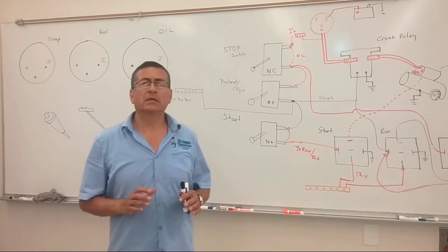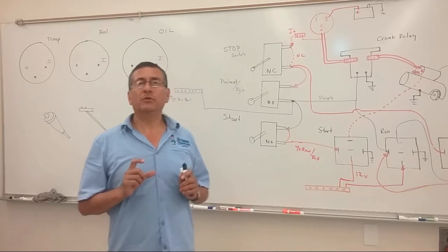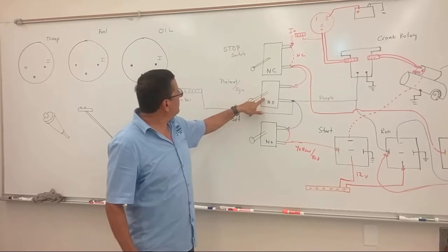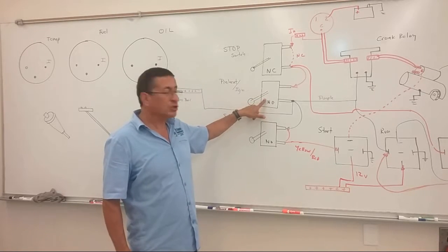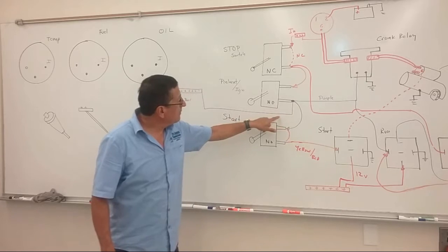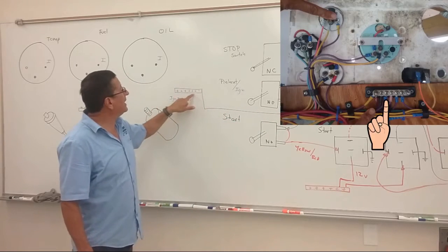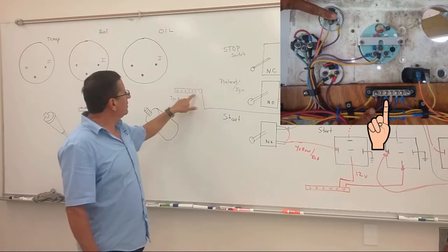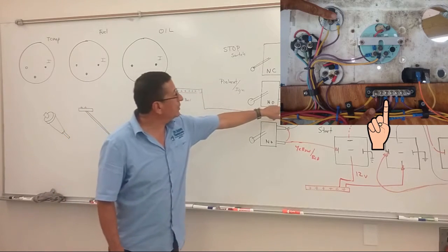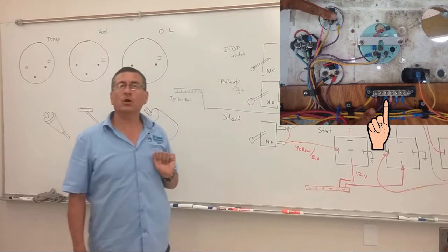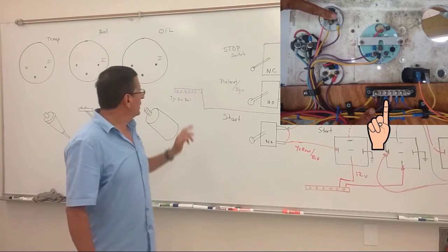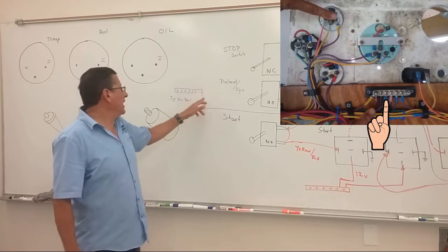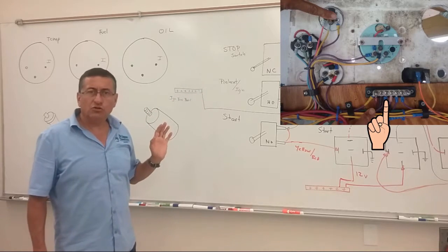In order to connect the oil pressure gauge, don't forget that when we activate the preheat or ignition switch, I feed an ignition bus bar, purple color. This ignition bus bar is coming from the ignition position in the preheat button or ignition button. That's the preheat. It is another positive bus bar, but the name of that positive bus bar is ignition.